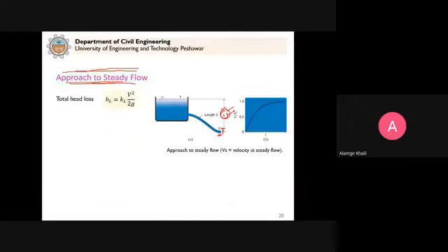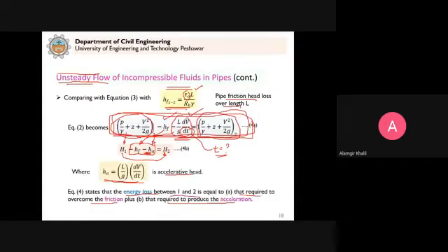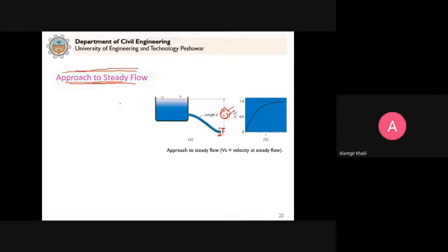So that's why, as I said, as we open the valve, flow will start, but as the velocity increases, the accelerative head is reduced by the fluid friction and minor losses. Because in the Darcy-Weisbach formula, it is proportional to V square. Clear? So that's why now we are interested in this topic to calculate the time. How much time will it take for this unsteady flow velocity to approach the steady flow velocity, which is the flow velocity under steady conditions.